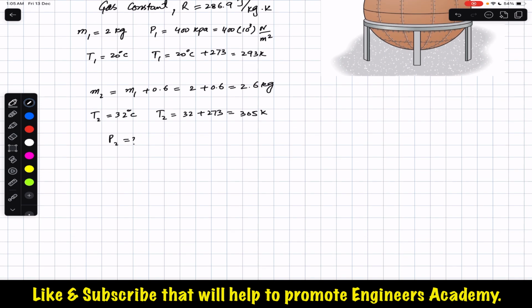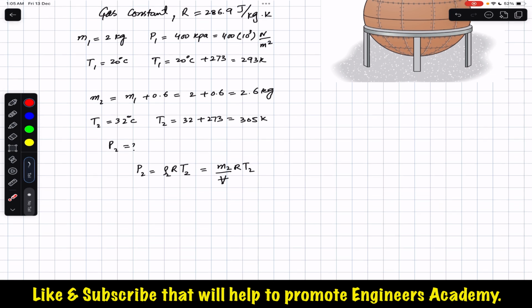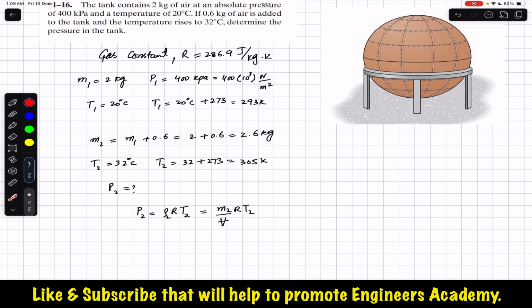Now using the gas law, we know that P2 will be equal to rho RT, or we can say rho 2 R T2. So rho 2 will be M2 divided by the volume of the tank, R into T2. So we want to find P2. In this equation we have M2, we have R, we have T2, but we do not know the volume of the tank. So since we have the same tank for both the states, the volume is constant, we have to find the volume using the initial data.